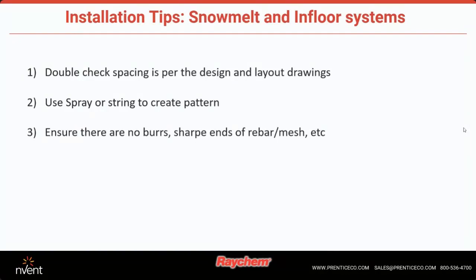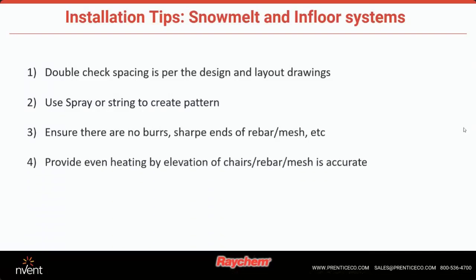Ensure that there are no sharp objects or ends. I have had projects, and in fact, every time I go to a job site to do my commissioning or pre-checks before a concrete pour, this is one thing that I'm very adamant about, making sure your cables are secured with the amount of cable ties that are needed, and that there are no cables that are near any of the rebar or mesh where the ends are cut off or sharp. I have had projects that has unfortunately been an issue, and it can cause wear and tear on that cable. So you want to be very cognizant of that.